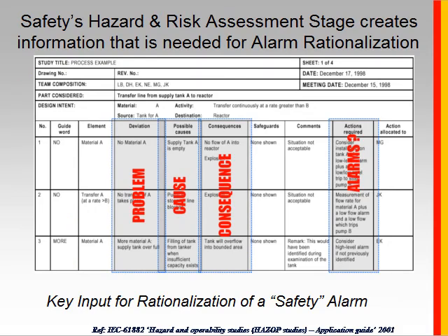And here's an example showing the results from a HAZOP, where the analysis is showing the indication for alarms to help as part of the safety instrumented function. So here's an example of where a HAZOP is used to identify particular alarms. Some of the other information that's in this HAZOP, such as the cause and consequence, is also very valuable and will be used in the alarm management lifecycle.